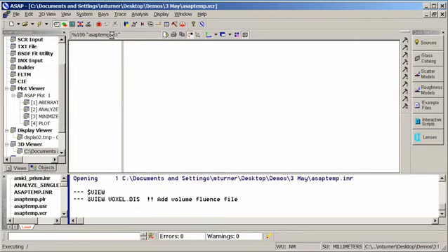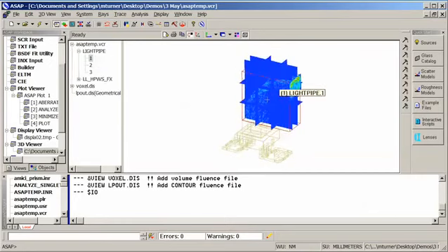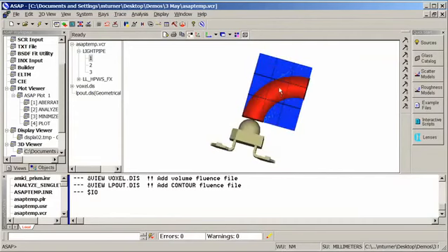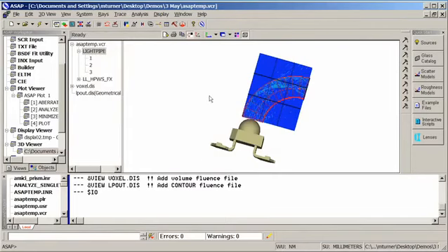What we've done is basically saved information about the rays as they propagate through the pipe at many, many different locations. What we see here is, for instance, the leakage that's occurring within the pipe. We can move it around and see information about the rays anywhere within the pipe. But there are a couple of things we'll notice. The first thing I'm going to do is turn the light pipe into a wireframe, so we can effectively look through the pipe.